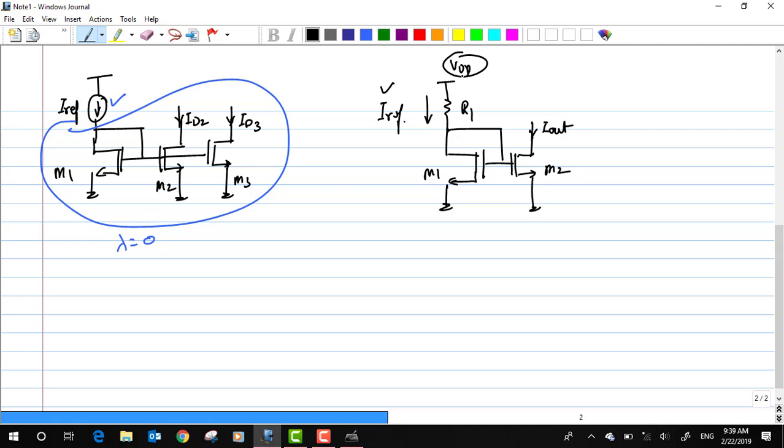Okay, so now in order to do so, let me try to represent the variation in my supply as something known as delta VDD. So when there is a variation, how will I model this M1 transistor, which is in diode connected configuration, and I'm looking at a small signal? Whenever there is a variation in my supply, what type of impedance does it pose?